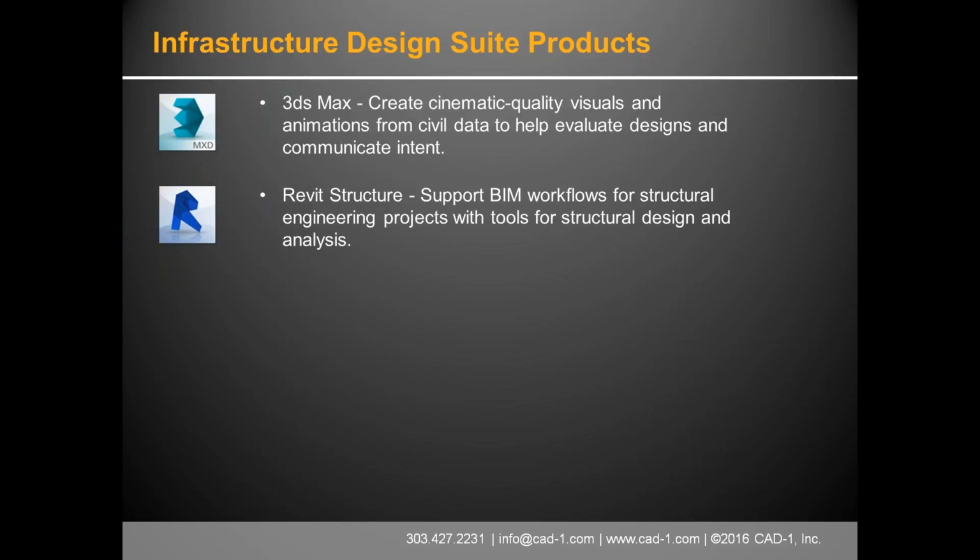There's a great connection with Revit Structure and Civil 3D through the bridge analysis, through the bridge modeling tool rather. So using the bridge tools, you can bring a Civil 3D model into Revit Structure and actually design a bridge. We can do that in Civil 3D sort of, but we don't have the same structural capabilities that Revit Structure has. We can't call this out as being a support structure or not. In Civil 3D, it's just a solid. So Revit Structure allows you to model it in such a way that it can then be put into an analysis piece of software to analyze the loads, find out what the moments are, the deflections, and those types of things.